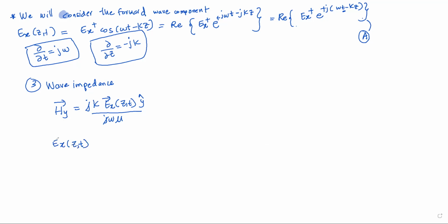It is an impedance value, and this impedance value is actually denoting the impedance that the medium has to the wave propagation. Now I have taken the ratio between the electric field and the magnetic field, and that ratio I can denote by omega mu over k.